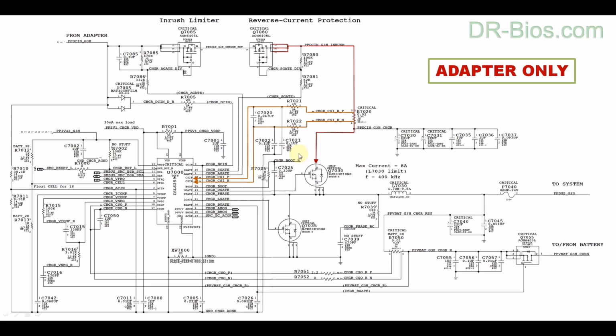During the process of generating reference voltage and drawing current from PPBUS_G3H voltage, IC gets sample from two sides of this resistor and measures current that's drawn from adapter.